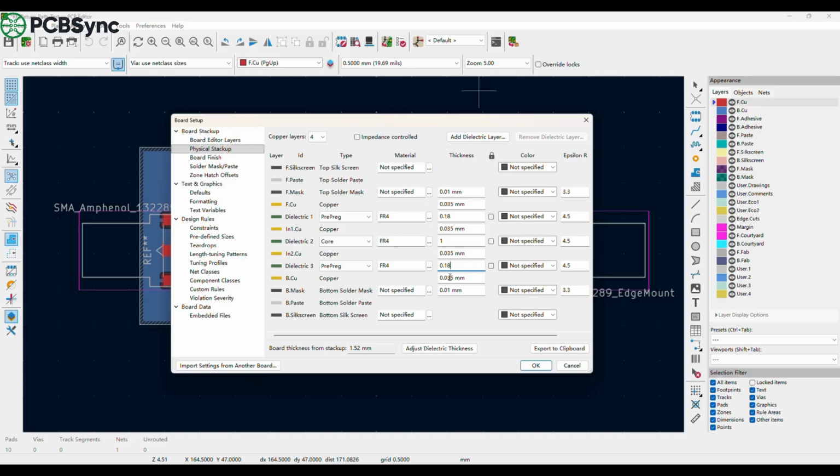So why do we set it to 0.18? It's simply because 0.18 is a standard spec supported by many PCB manufacturers. A 50 ohm microstrip is also easier to achieve. In short, this is one of the most common configurations for RF engineers.